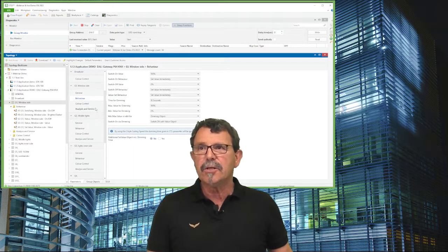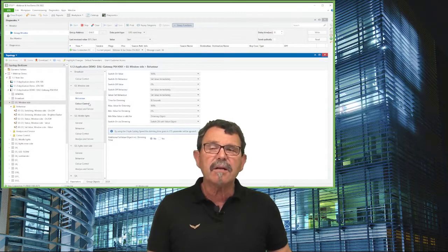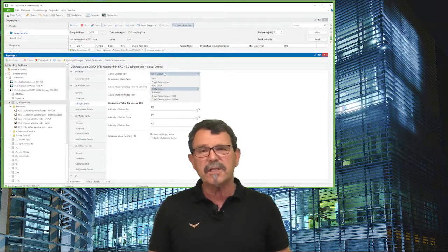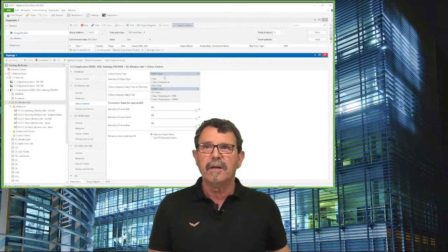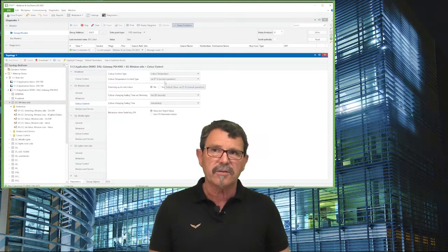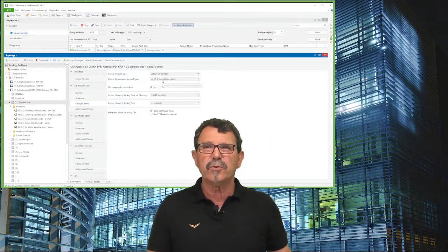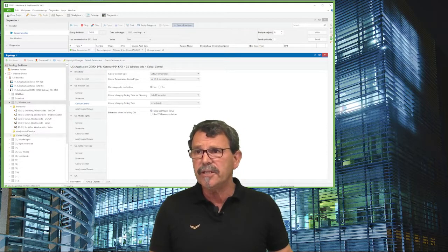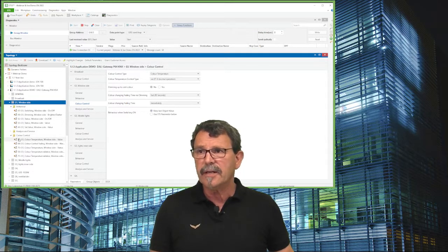Okay, so then you discover here color control, and this is finally where you can choose what kind of control commands you want to offer or to activate. If we intend to do color temperature control, this is according to data point 8, which we are finally supporting. So this is normal operation, and the communication here is, if I open here, color control,